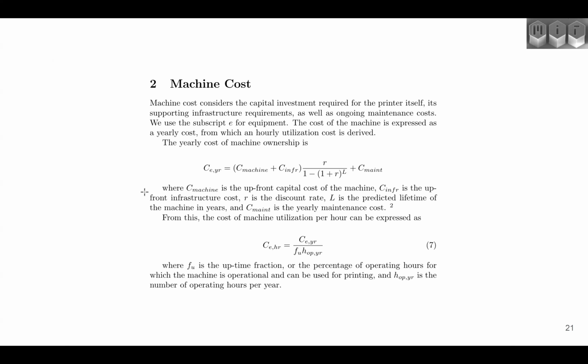Whereas if a machine is not dedicated, then we can do a generic estimate and say we assume the machine is going to be running for this many hours in a year, calculate the dollar per hour, and then treat things that way, where even if my parts or one product is only taking 50% of the capacity, it's not paying for the other 50%.